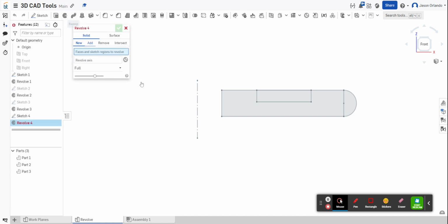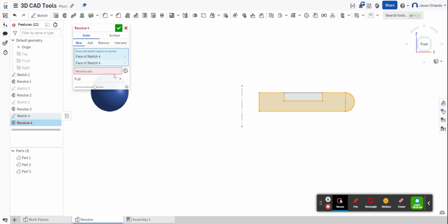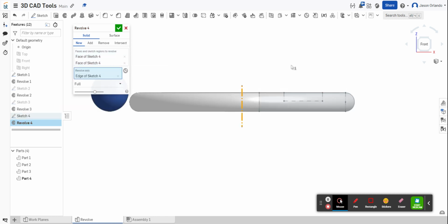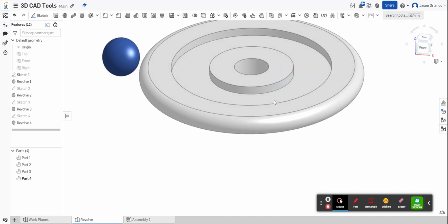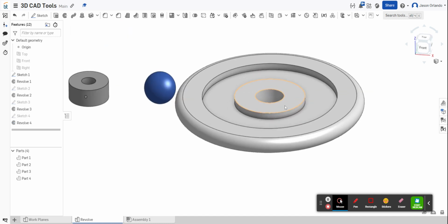And this is very similar to the geometry that would create the wheel for our train project later. So I would revolve. I'm going to revolve this space, not that rectangle. That was there to create a subtractive region that I don't want to revolve of the big rectangle. So I want of the big rectangle just this, not that, and then this semicircle on the end. I will then choose the axis over here, and I get this shape that looks like a plate at the gym, like a big 45-pound plate that I lift so easily.